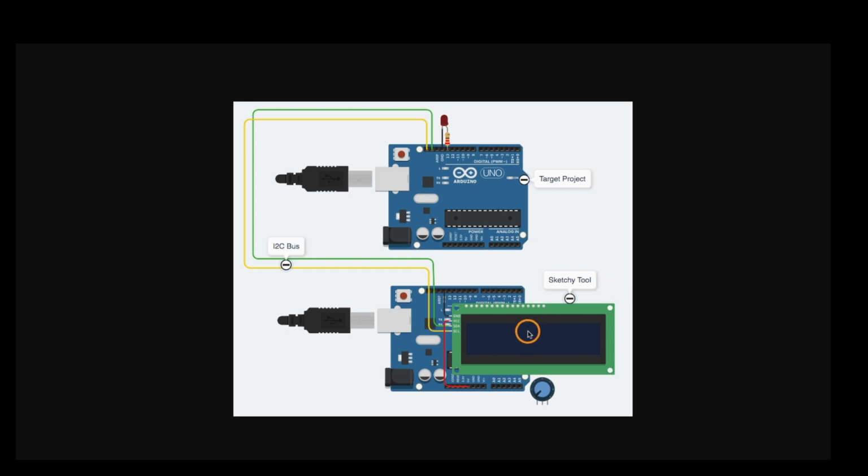So this tool just puts a hook over I²C into this other project, allows tweaking a variable on the fly, so we don't have to reprogram this until we decide on a final value that we can hard code later.